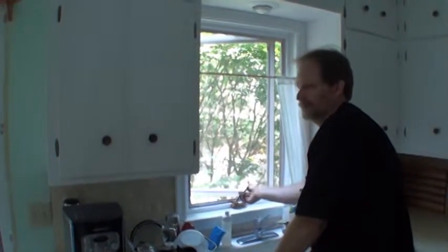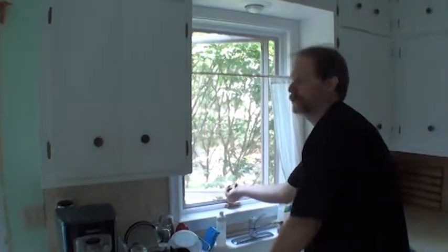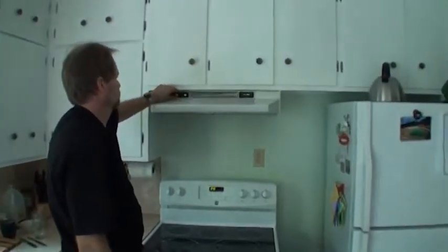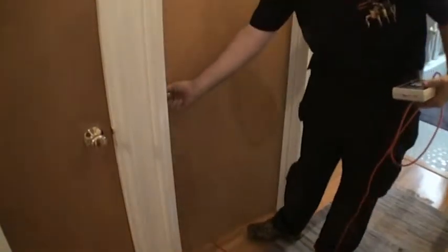Set up the house for winter conditions. Close all windows and exterior doors. Turn off all exhaust fans. Turn on the furnace air handler. Place the manometer hose a minimum of 3 feet into the room away from obstructions in supply and return grills. Close the door and be careful not to pinch the hose. Connect the hose to the manometer.